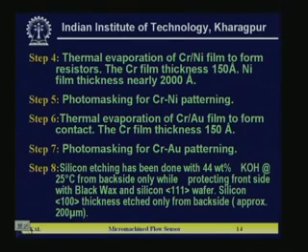The chromium film thickness is 150 angstrom, and the nickel film thickness is nearly 2000 angstrom. Chromium is required for adhesion, and nickel is basically your thin film metallic anemometer, which is the sensing element. If you want to pattern this kind of structure, you can face a little bit of a problem. Because you have already patterned the oxide, there are uneven places on the top and bottom surfaces where you have made grooves by removing silicon dioxide.